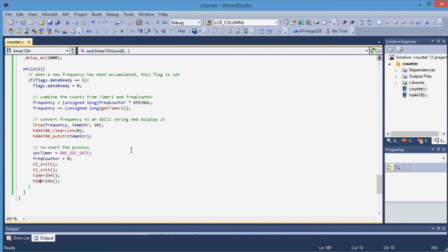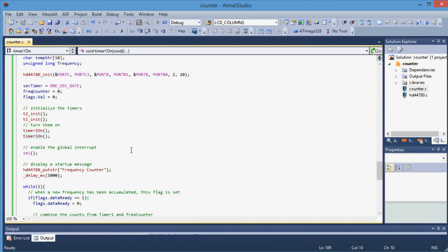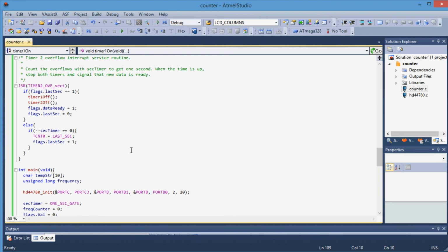Where the problem occurs is when you shut the window, and that occurs here in this interrupt service routine. Now when the conditions occur that the interrupt is generated, it takes some time for the microprocessor to actually generate the interrupt and vector into the interrupt vector. What the processor has to do is finish the current instruction that it's working on.